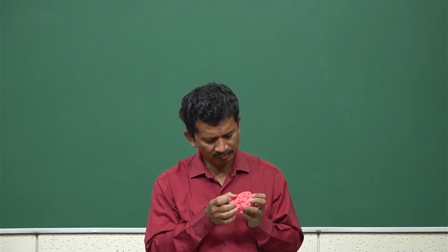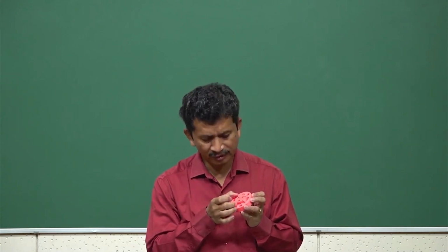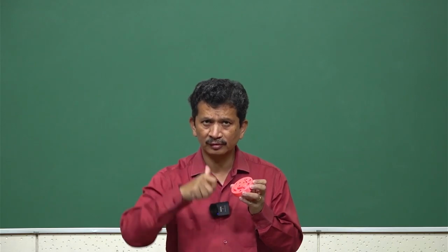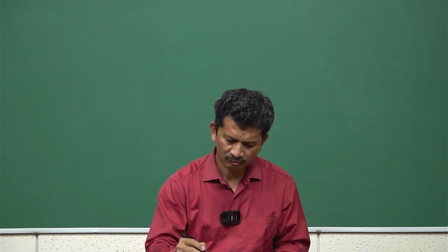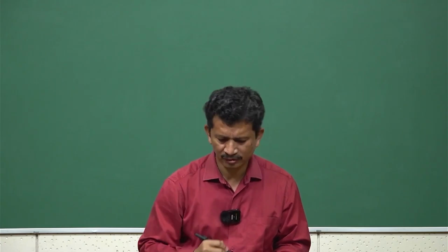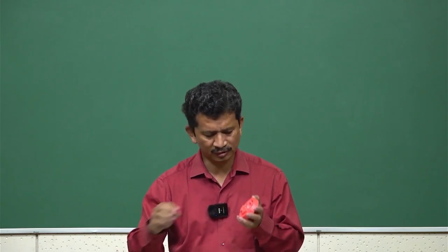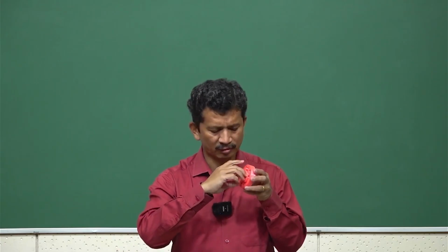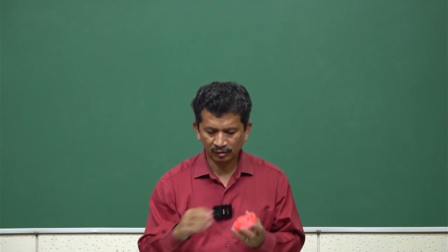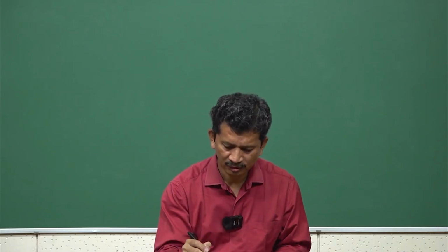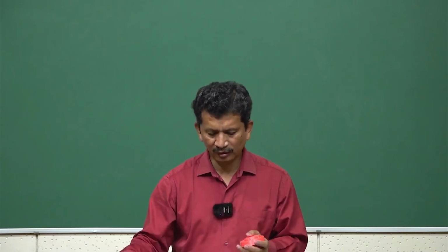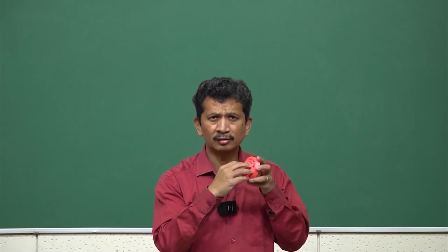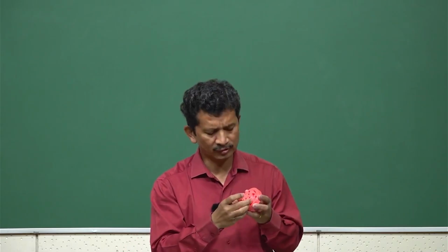But the moment I apply a nesting force, in this case just clockwise, to the red object, if you just give this torsional moment to the red object, it comes in contact at these 3 points. The moment you establish these 3 contacts, it will always go to the center.